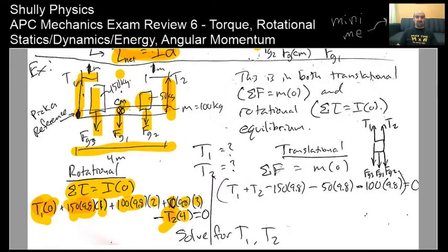Now, if you did use the center mass as your reference, you would have different torque arms, but you would also have an equation with 2 unknowns, and you wouldn't be able to solve it. So solving this equation over here that I've formed will give us an answer for T2, but it doesn't give us an answer for T1. You see, it's blocked out over here. It's a 0. So what you're going to have to do is form a second equation.